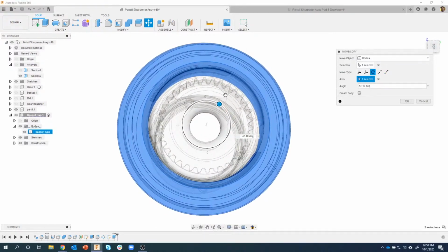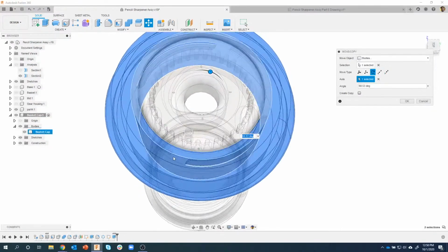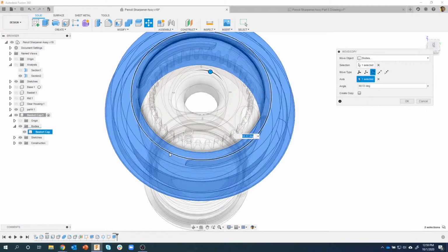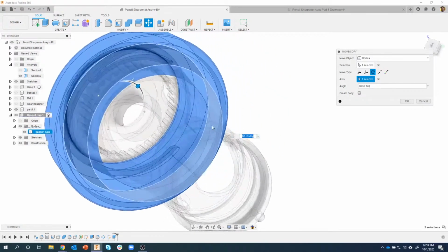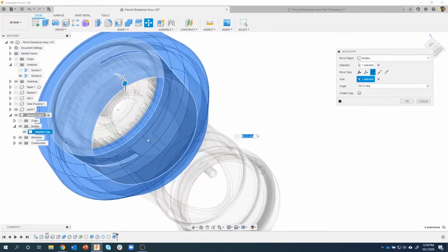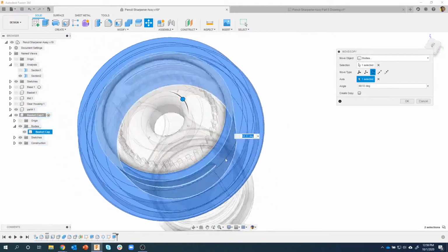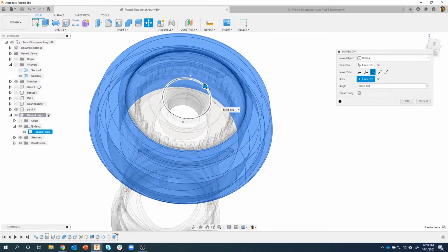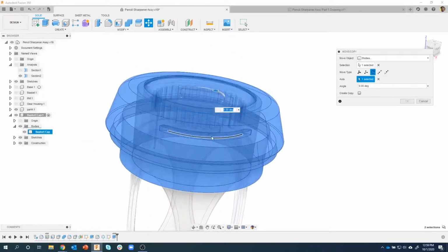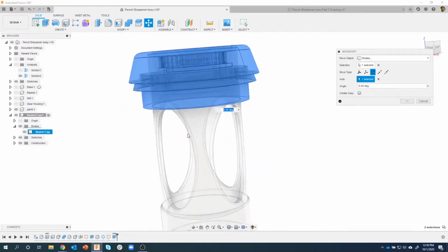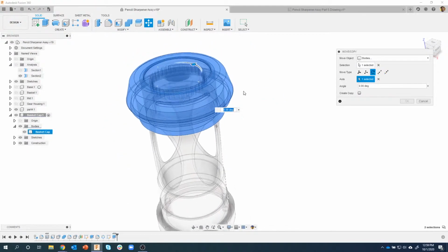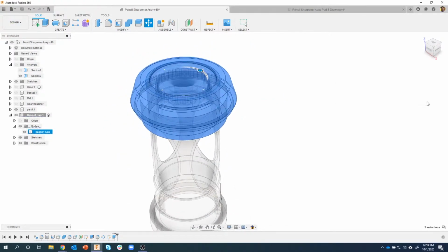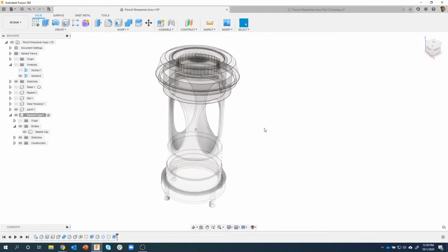As I rotate this around, we can see, sure enough, that that thread is rotating, and we have clearance past that L and clearance before we hit that L over there. So you would basically drop this cap down and then rotate it into place, and that's how it gets held into place. And we used the information from this other part to help us design the cap.